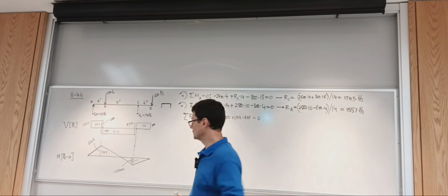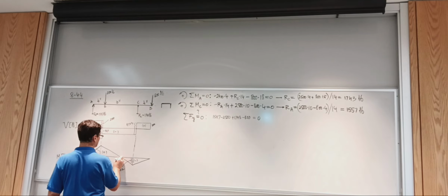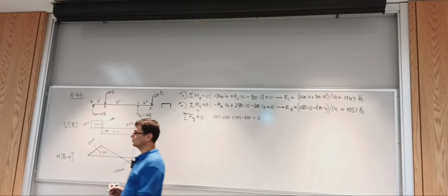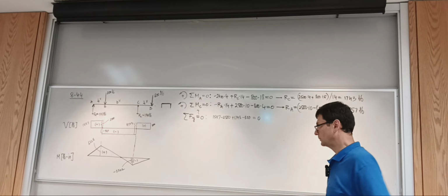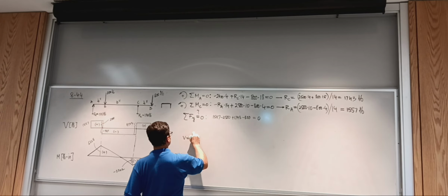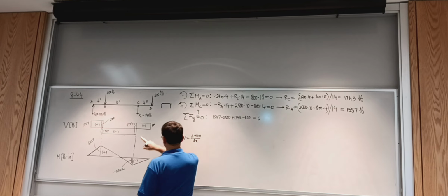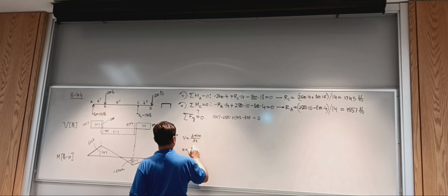And we have the peak moments. How do we get where the moment goes to 0? That's where the slope, if you remember, we have, so V is, in general, dW of x over dx. X is the axis of the beam. And then we have M is dV of x over dx. And then I have, how's it go?